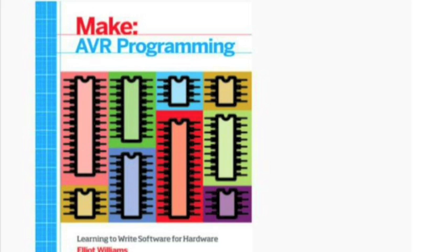And maybe the last question I'll take is, have you ever used AVR libc? Does it have a small memory footprint? I think so. The trick is that if you set the compiler options right, you'll only use the functions that you use. And so in that sense, you can have as small a memory footprint as you'd like. On the other hand, as I said before, things like printf can be real beasts.